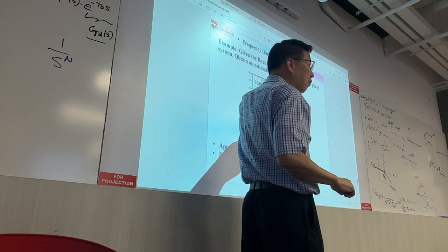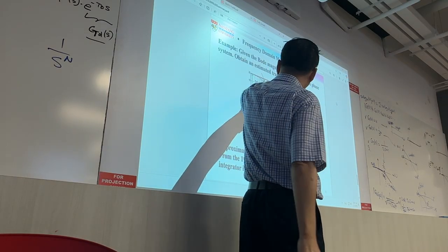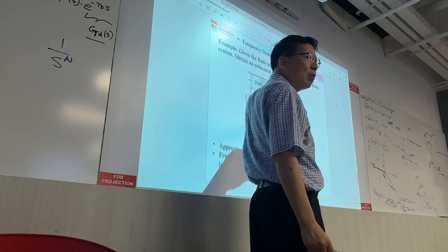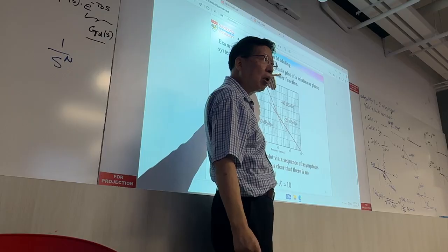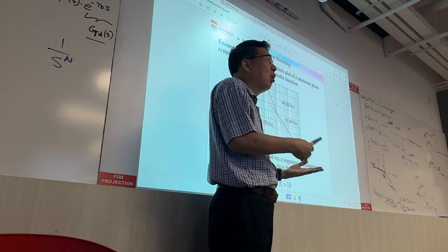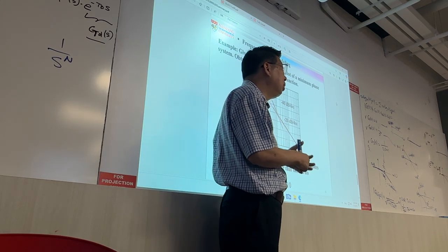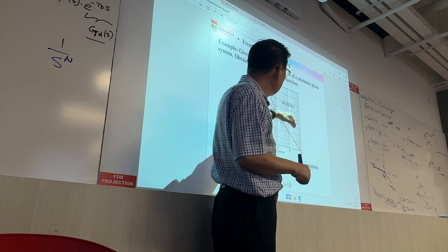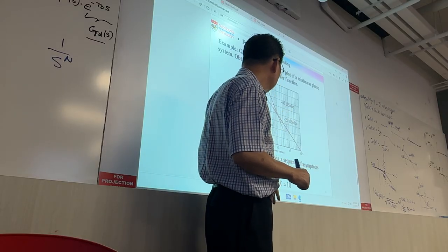You know this corner frequency, because from the construction, we know that at corner frequencies, we get new contributions, which will bend the Bode plot up or down by a multiple of minus 20 dB per decade or plus 20 dB per decade. Okay? So these are the information we get.